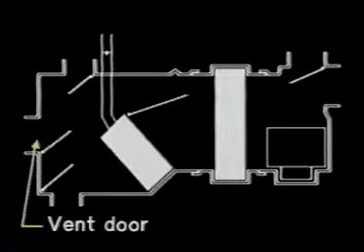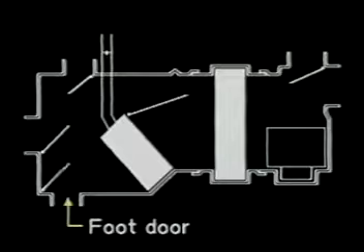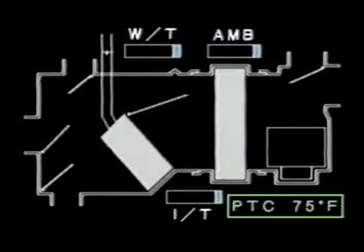Let's look at the differences of operation between the 75 degrees Fahrenheit setting and the 85 degrees Fahrenheit setting in the winter. First, let's press the auto switch. Then let's set the temperature to 75 degrees Fahrenheit. In this condition, the automatic air conditioner immediately reacts to make it warm because the in-vehicle and ambient temperatures are low, and there is a large difference from the set temperature.